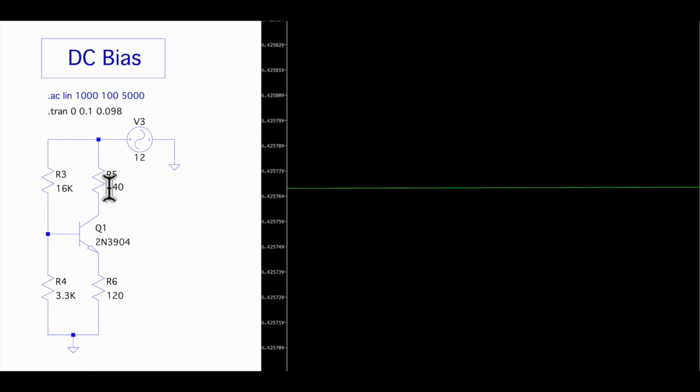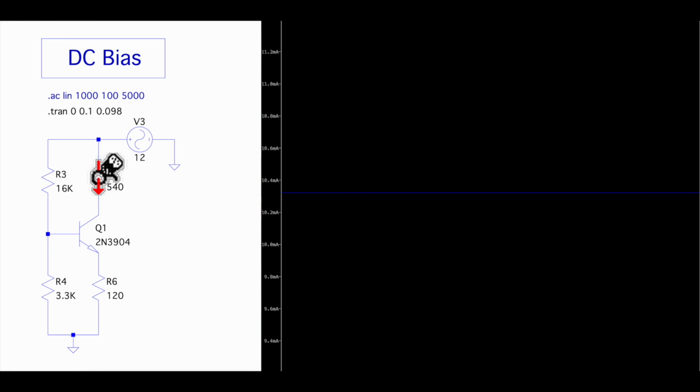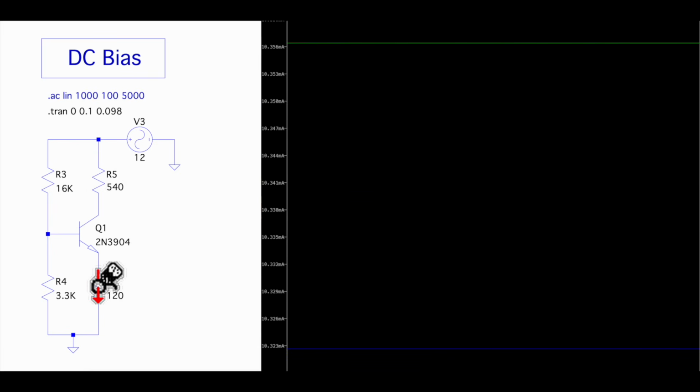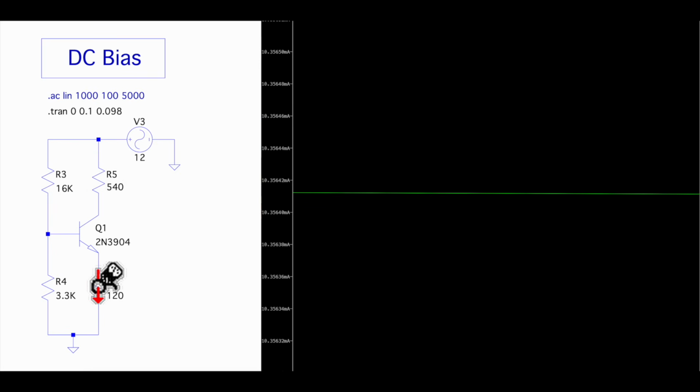And we can check the currents. These are a bit pixelated because this plot is so huge. Yeah, 10.3 something there, so that's fine. Now, the only thing which is different here is the current through this voltage divider is not 10 times the base current.